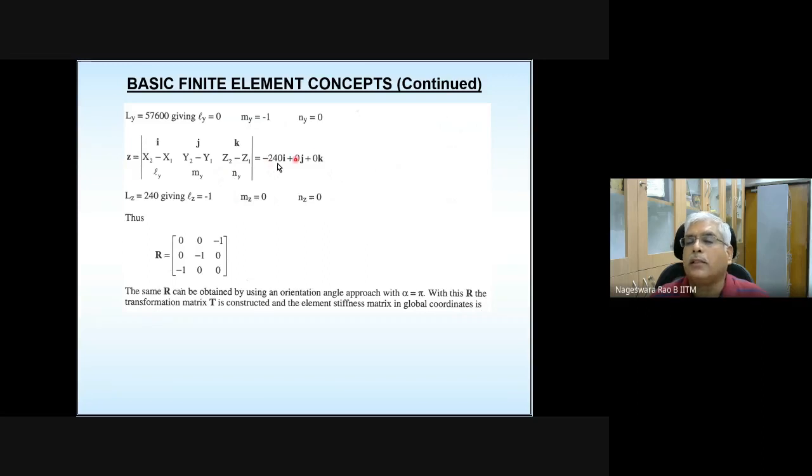And normalize this vector. Here the unit vector along the small x-axis is not used, a vector is used. So you need to normalize it. If you normalize, you are going to get Lz, Mz, Nz. So once you have all of this, Lx, Mx, Nx, Ly, My, Ny, Lz, Mz, Nz, you can write the rotation matrix for this single element.